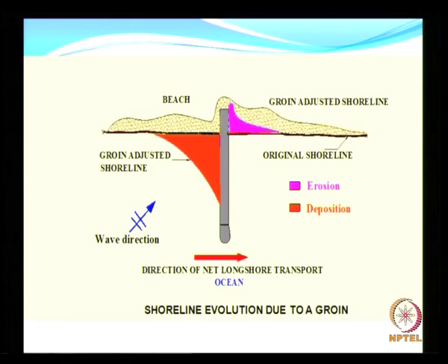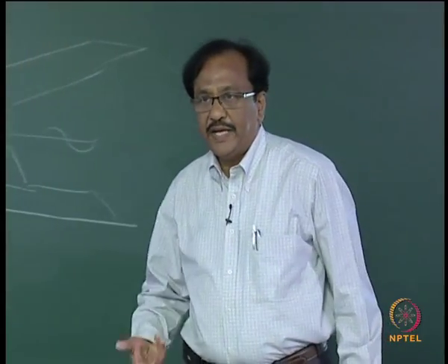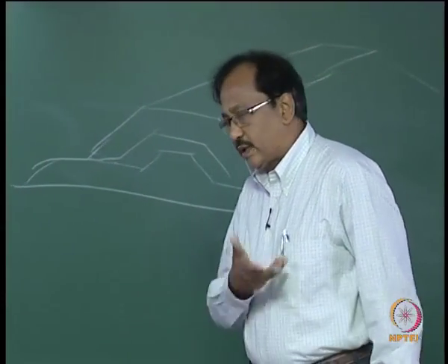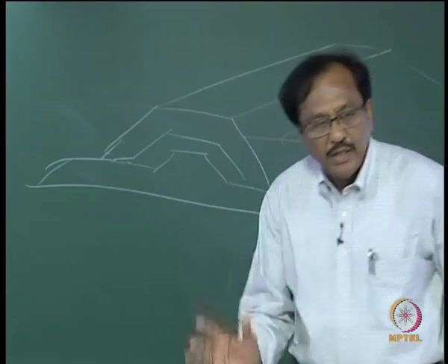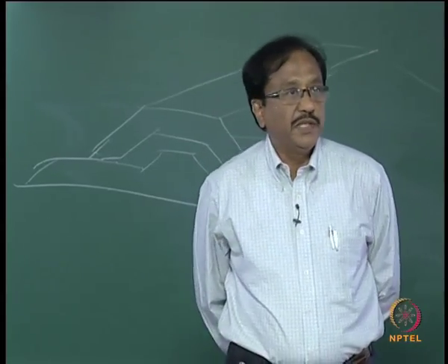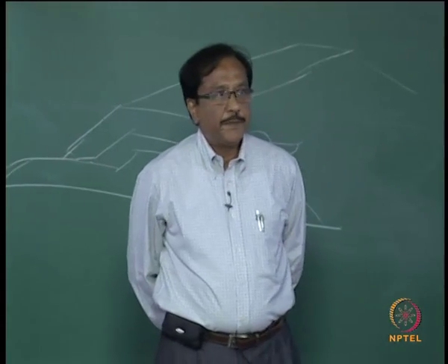So, you see the phenomenon of diffraction permits the wave to propagate into the sheltered area, remove the sand, and then come to shore and to the surf zone, and then the longshore currents keep driving the sediments.